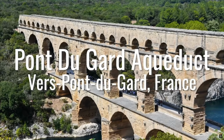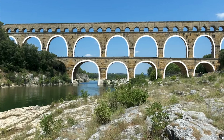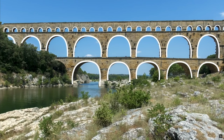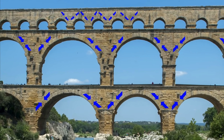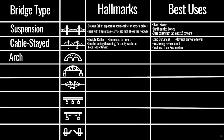So the aqueduct is another example of a stone arch bridge. Here we have a series of stone arcs that allow the force to be transferred throughout the arc. These smaller arches then, of course, transfer the load to the bigger arches. It takes advantage of the opportunity of breaking up the spans such that so much isn't required of a single arch. It's also redistributing the load across the smaller arches so that as they're transferred upon the bigger arches, the larger arches can then act as piers that are spaced further apart, giving greater spans.